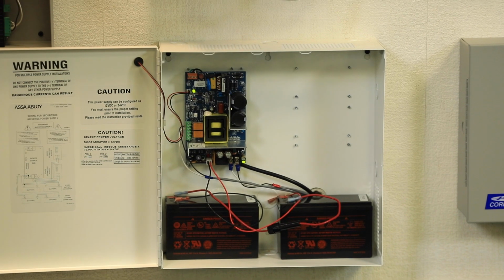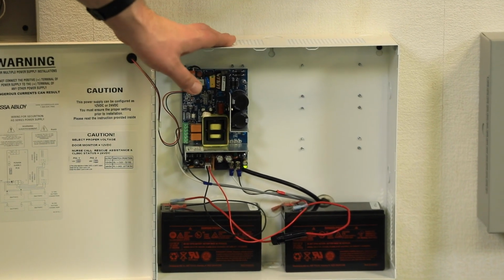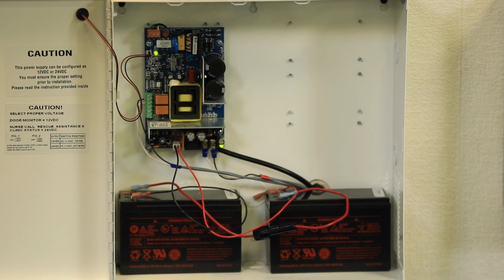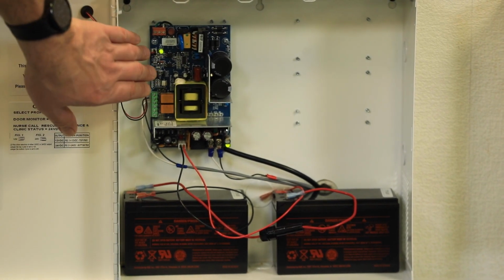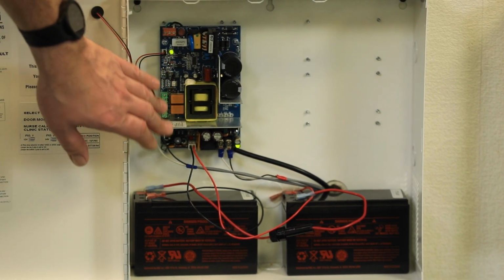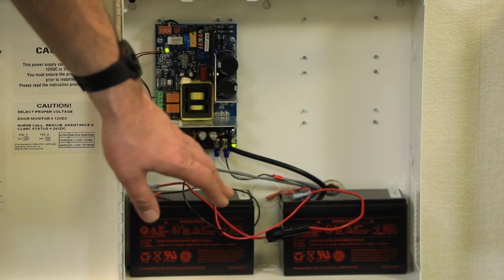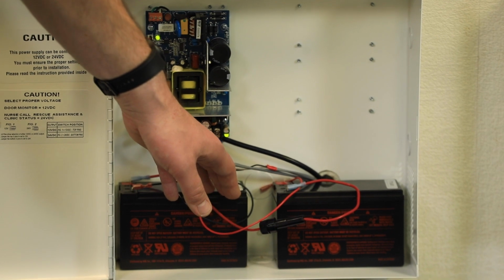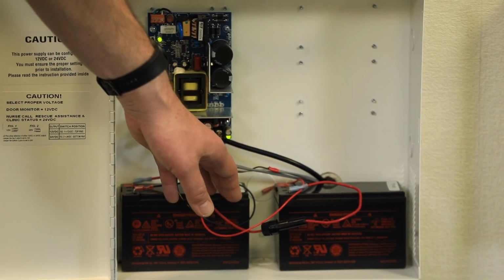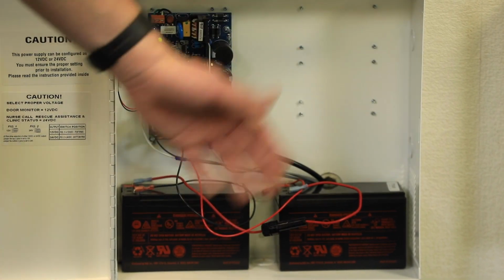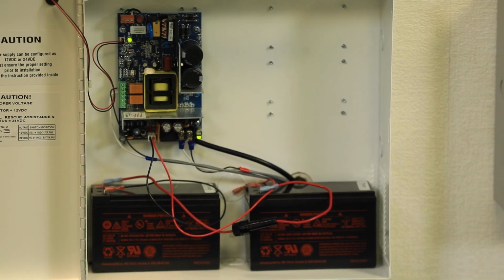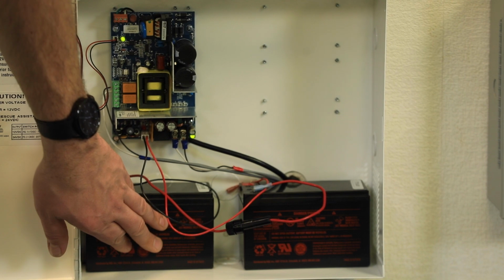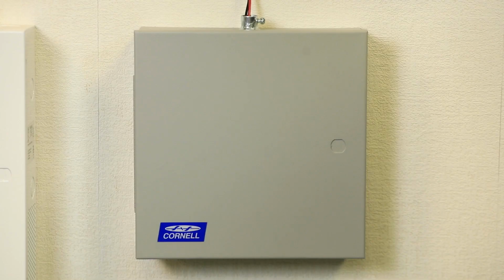Each expansion switch will include a power supply with battery backup. Now, the power supply requires 120 volts AC input power and will provide 24 volts DC output power. The power supply constantly keeps the batteries charged until they are being used for emergency battery backup power. Each pair of batteries typically provides up to 3 hours of battery backup time for your expansion switch.